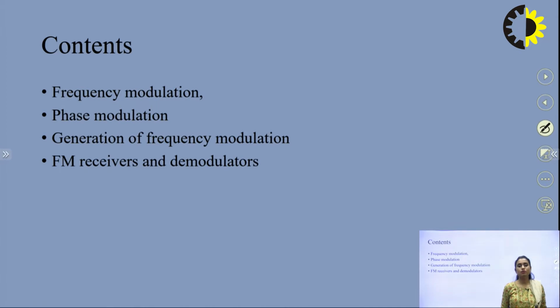Now the question is, how do we do modulation? If I take a general naturally available signal, like a pure cos wave or pure sine wave, I may represent my pure cos wave by x(t) = A cos(omega t). If I talk about a wave, it has these two properties. One, the amplitude of the wave, another, the angle of the wave. So when I talk about altering the characteristic of a wave, I would be either altering the amplitude of my carrier wave or its angle. These are the only two ways of altering my wave.